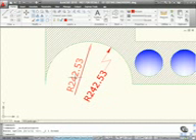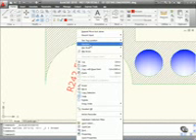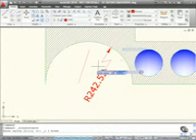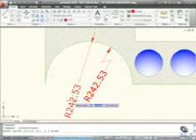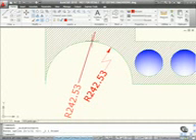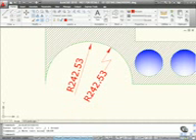I can also do that with this normal radius here. Click on it, right click, dim text position, move text alone. I can pop that on the end of the radius line. As you can see, that looks much neater, but look, as soon as I move that one, the normal radius does that. That is why you use a jogged radius on a large set of radii like this, because the jogged radius sits neat and tidily like that with a temporary center override. If I just undo that step there, as you can see, the arrow comes back in again.